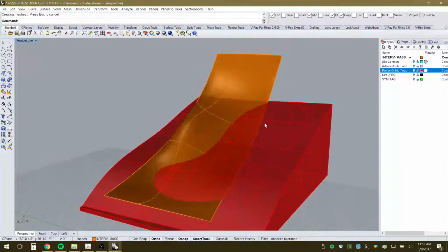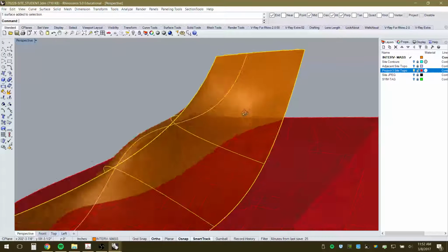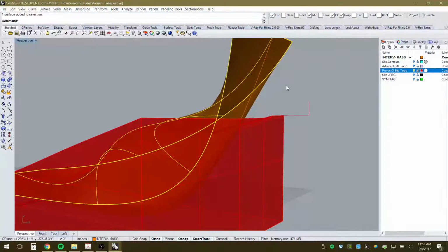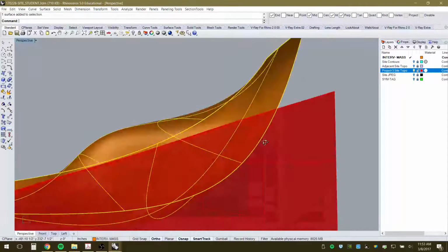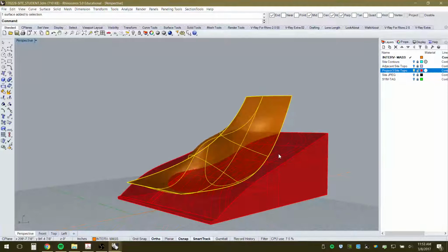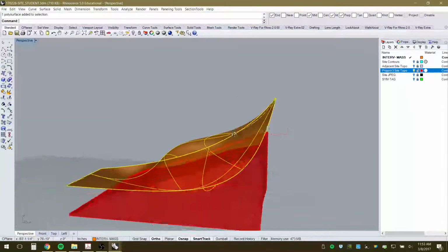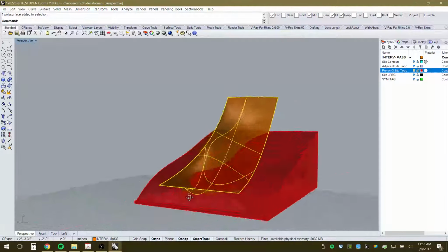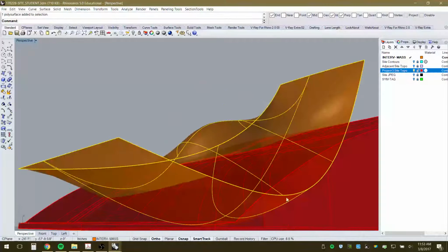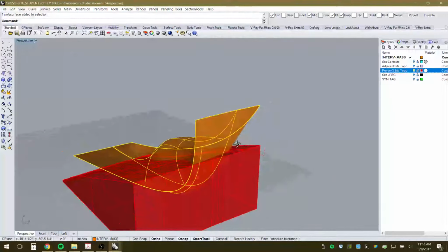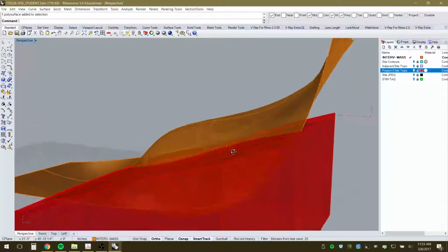So before I go any further, I'm going to go ahead and select both of the new surfaces I just created, and hold my shift key down to select both of them. Make sure I have the surfaces. And I'm just going to type in join, or of course you could use the puzzle icon there. So now that's considered to be a solid. Because I use the same curve on the edges here, I know that that's a closed seam. So basically this overall geometry now is watertight.